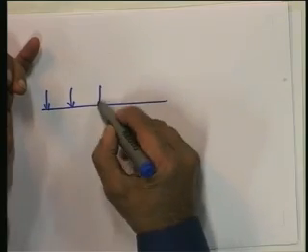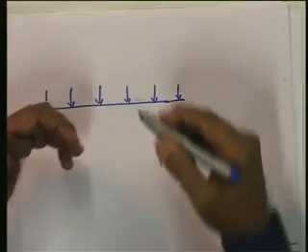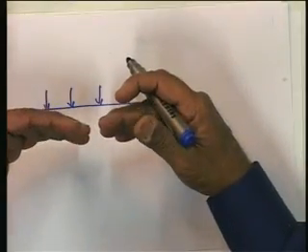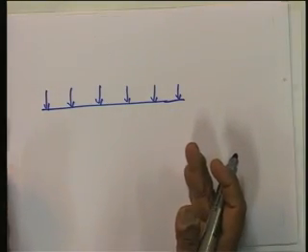You remember that when we were dealing with stress distribution in soils, and when we were talking about a uniformly distributed load over a large foundation on the surface of a semi-infinite soil medium like this, a large area which is subjected to a load essentially causes transfer of load in the downward direction, but due to Poisson effect it may also affect the lateral directions.